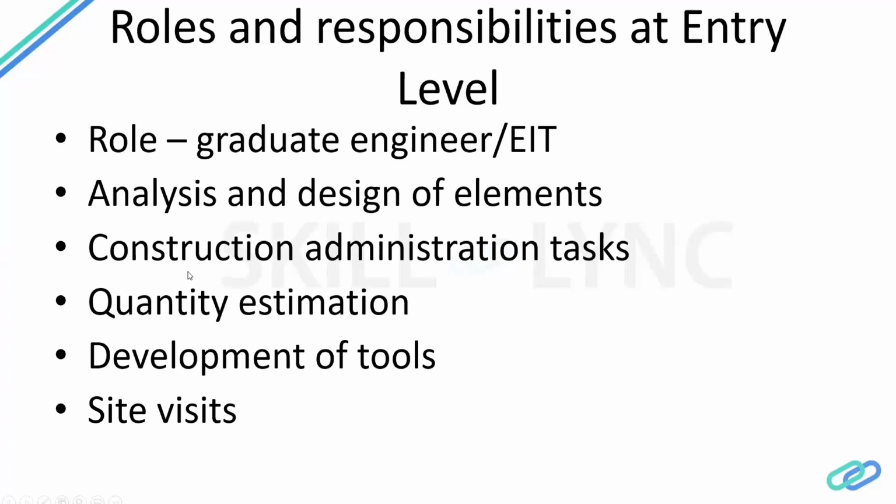In addition to that, there is some quantity estimation task as well, or BOQ as they call it, bills of quantities. Say it's an RCC building, you have to make sure of the kg per meter cube of reinforcement that you're using, or the kg per meter cube of slab, and things like that. So, the concrete quantities, the steel quantities, or whatever. That's something we have to do to make sure that whatever we are doing is in line with what was expected.